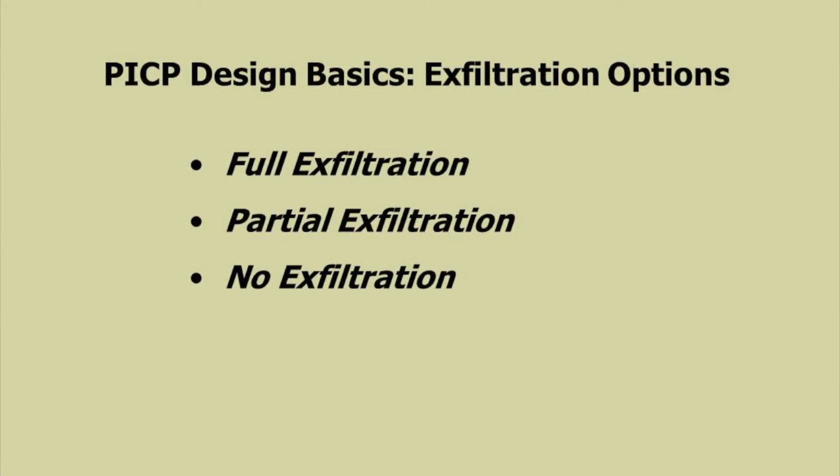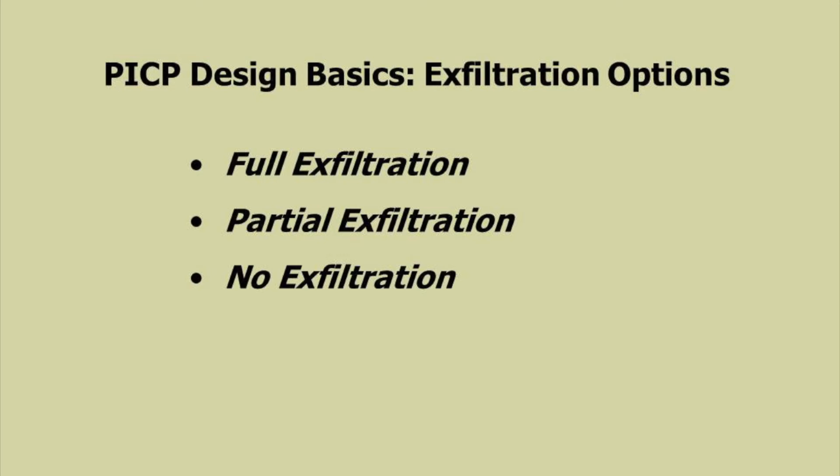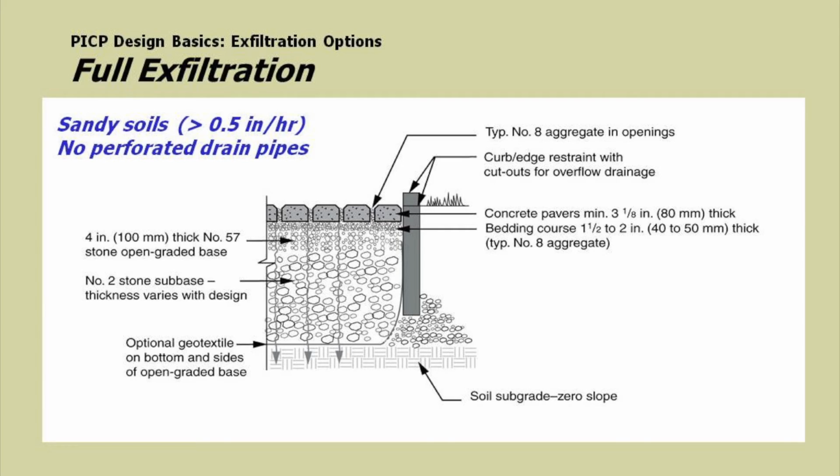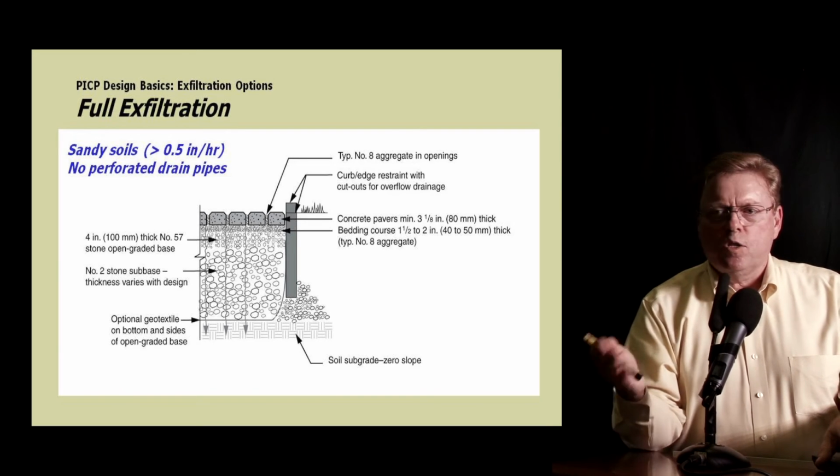Design basics: 3 ways of looking at permeable designs for pavers, they're in the manual. Full exfiltration, we used to say that was where we had pretty sandy soil with infiltration over 0.5 inches. I think the LID manual changes that to 0.3, if I'm not mistaken. And we're seeing improvement based on some of the work that Curtis is doing and others, that we can get good drainage and good infiltration from systems that are even less than that. But the LID manual allows for down to 0.3 inches per hour. You use full exfiltration,